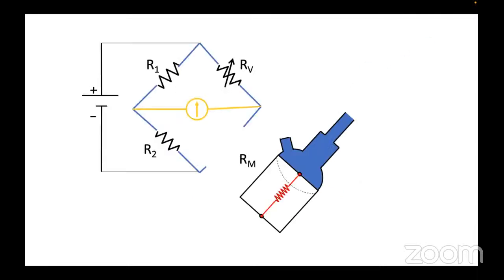So this is a variable resistance, also called a strain gauge, in a transducer. Pressure is applied, the diaphragm moves, the wires get stretched, and so the resistance also gets changed. That's part of the Wheatstone bridge. And then we have the variable resistance, which needs to be changed accordingly to maintain a balance across the bridge. That's how blood pressure is monitored. Obviously there are other ways of monitoring it. You can have capacitance instead of resistance in a similar way, but classically it is described as a Wheatstone bridge.